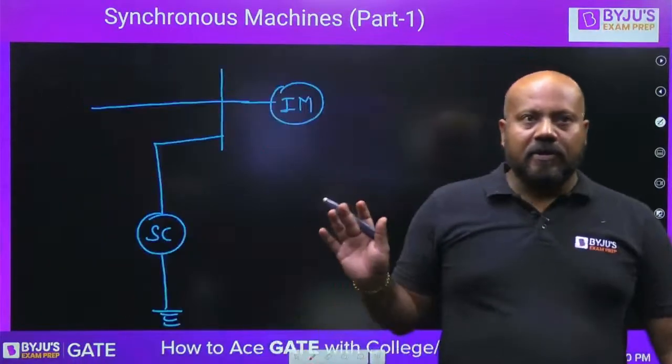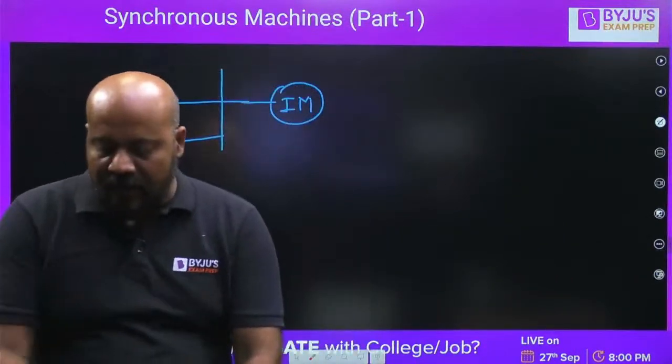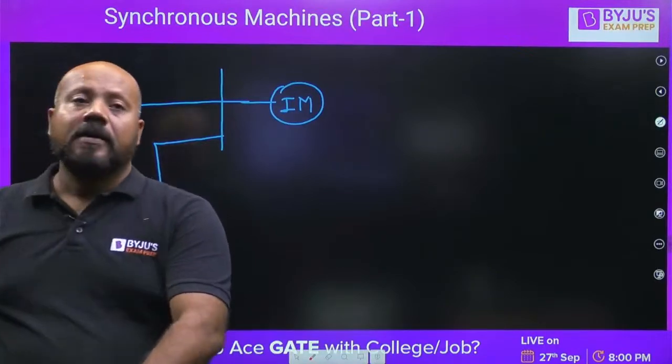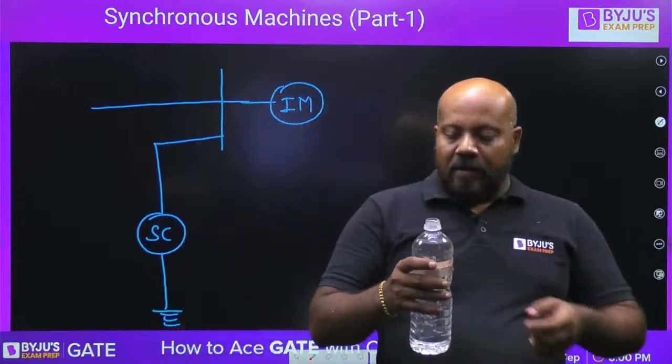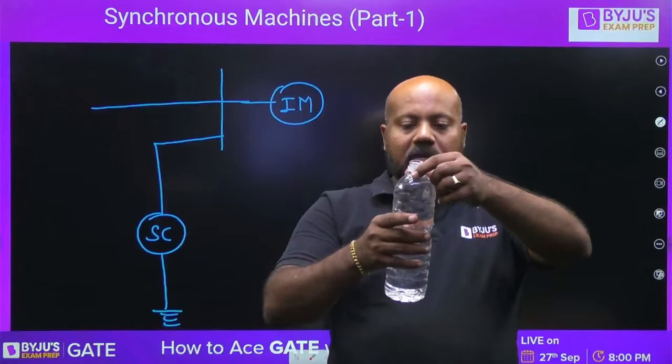Are you getting this? But if you see this question, the data is given such that there is a confusion: he is talking about synchronous condenser, but the data he is mentioning actually belongs to a synchronous phase modifier.